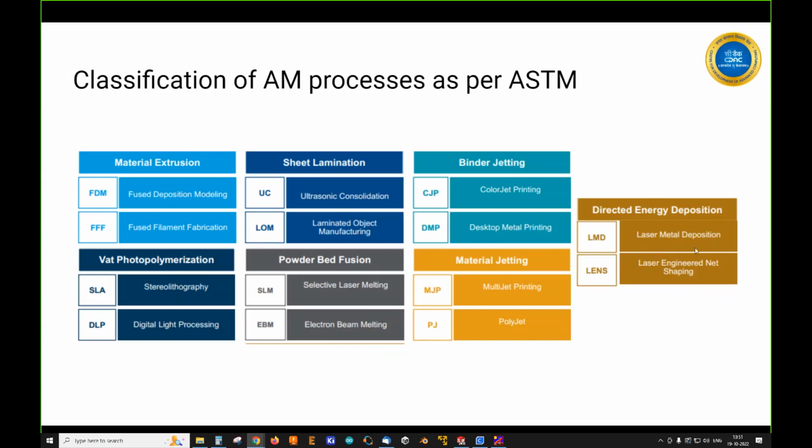That material is melted using a laser or a nozzle with some kind of heated element or thermocouple, and it is poured onto a build platform. Instead of joining two parts together, the metal is melted and poured layer by layer in order to create the functional part. That is called direct energy deposition. But the defect of direct energy deposition is that we get very low accuracy, because we cannot create very minute or very fine layer parts using it.